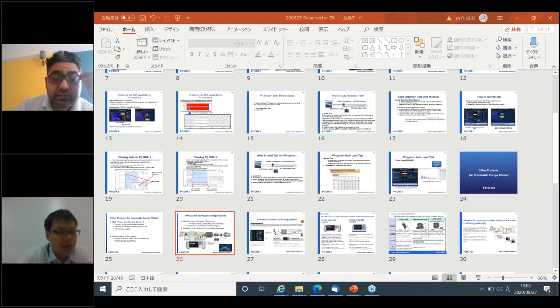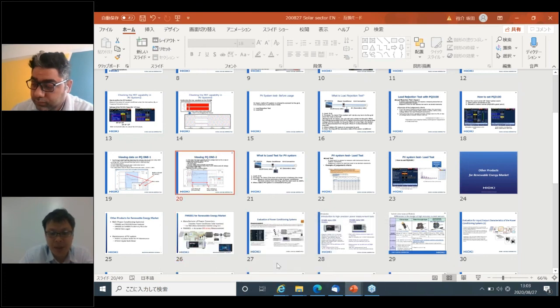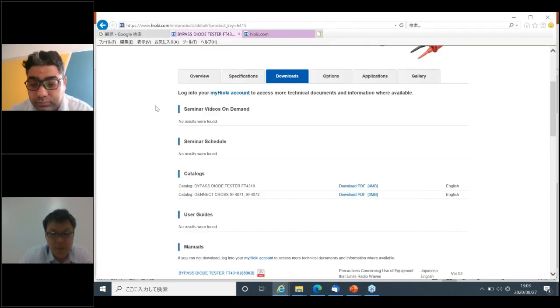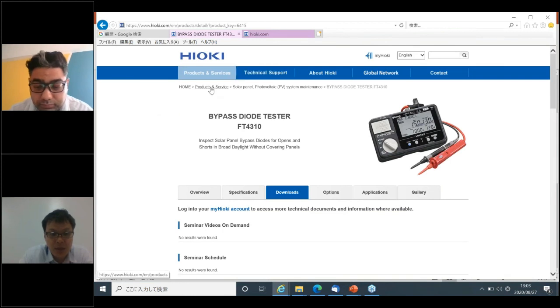If we are talking about EMI, maybe it is in the electrical component world. In that case, pre-check the electrical components like the common mode filter or RF inductor, and according to the specification, you need to control your EMI noise. As one example, we have an impedance analyzer. This product can check the impedance of this kind of electrical component. For example, I will show the product.